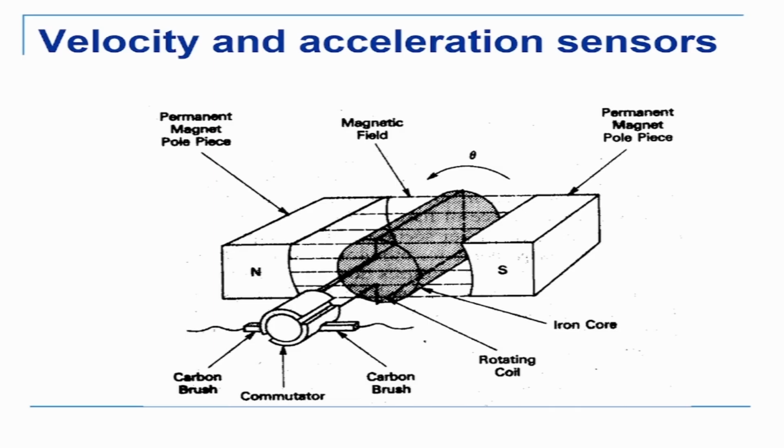Now you would have studied DC motors at school itself. And how a DC motor works, you know that we give a voltage in. So I'm giving a V in, plus minus here, and there will be a voltage in this coil. Because of this voltage, a magnetic field will be produced. On a conductor, when we have a voltage, a magnetic field is produced. The field produced by the rotor will interact with the field produced by the stator, which will cause a moment on this rotation. That is basically how the motor rotates.